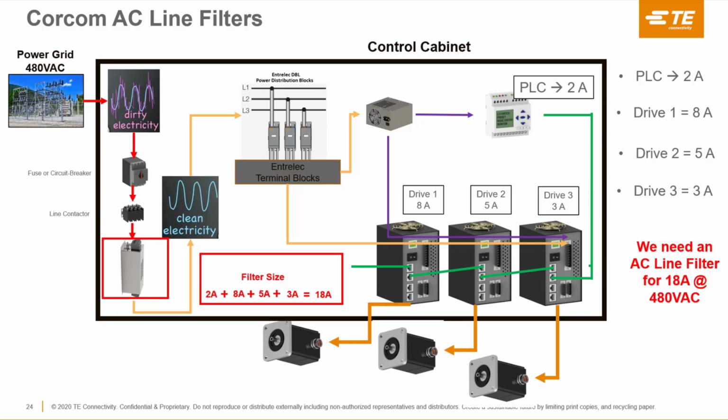Always keep in mind, I think best practice is to always try to size up a little bit, because you might talk to a customer one week and then follow up with them two months later, and they say, hey, last minute the project manager had us change some stuff. We had to add another drive that's pulling 2 amps. So all of a sudden there you have 20 amps.